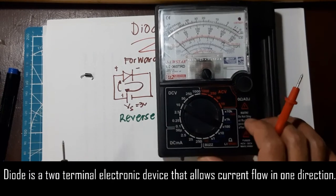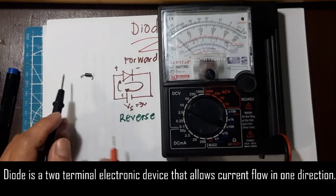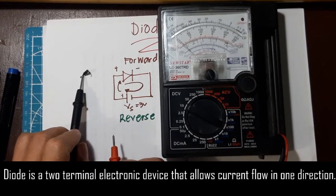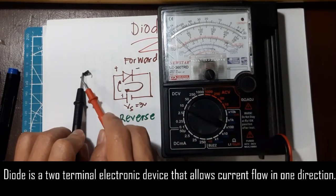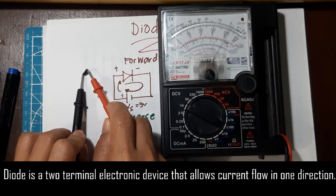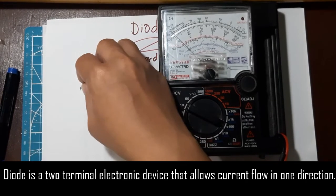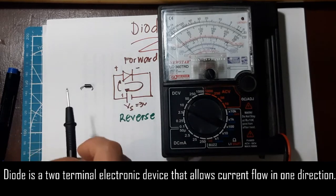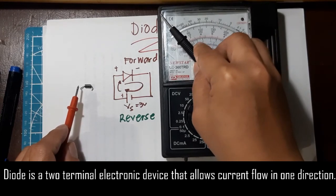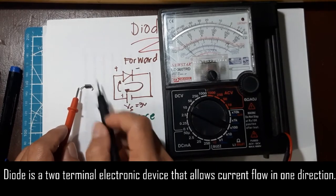Okay, so now to test, if this is my positive and this is my negative, I have to put the anode here into my black probe, and this should give me forward bias. See the deflection there, so meaning it's forward bias. Okay, now if I reverse the situation, this should not give me an indication of low resistance. Otherwise, we can conclude that the diode is defective.